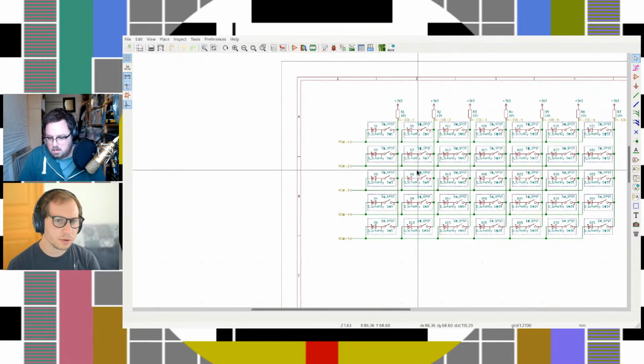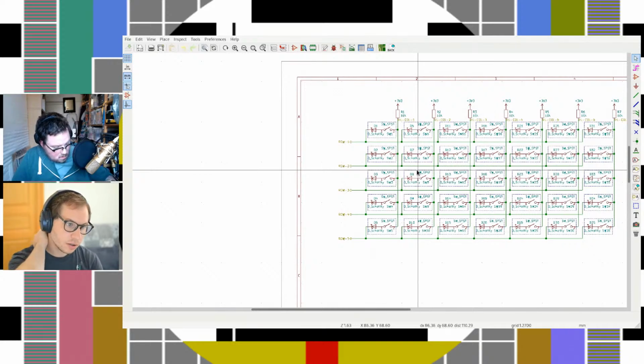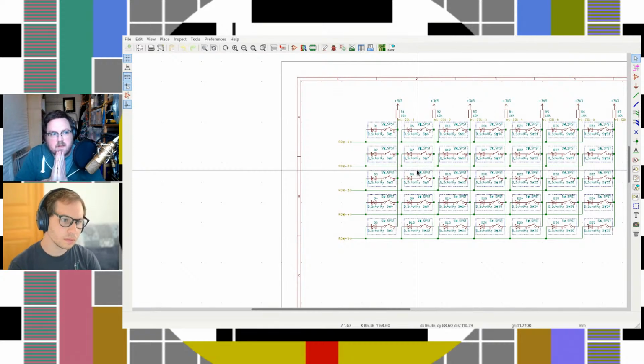And what is a reasonable frequency to scan through the columns of the matrix here? I'm sure there's a specific way you can figure that out. There is some maximum rate that USB will allow for keyboards, and I'm sure there is a number, but I don't know it. Honestly, something like 10 times a second would give you up to 100 milliseconds of lag. So 100 times a second would give you up to 10 milliseconds of lag, and 1,000 times would give you 1 millisecond of lag, if you were able to do a full scan at that frequency.